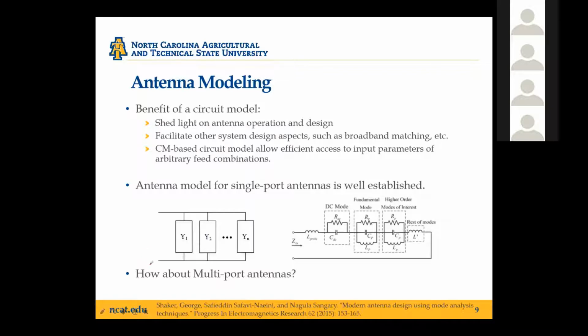You can model its response as a series resonance in parallel, or a parallel resonance in series. And with circuit models, we get the benefit of gaining insights on the antenna operation, and sometimes a circuit model can facilitate broadband matching circuit design as well.